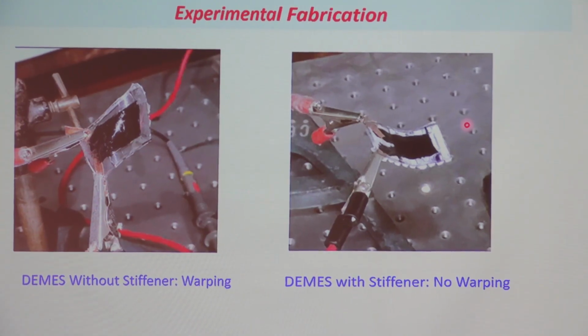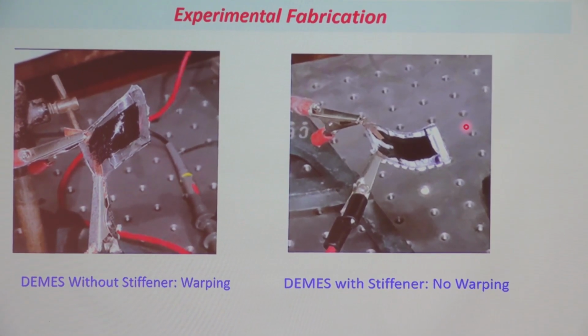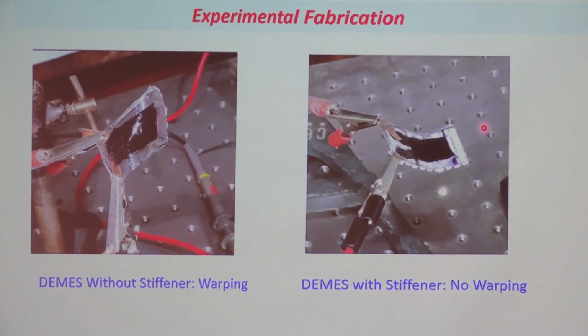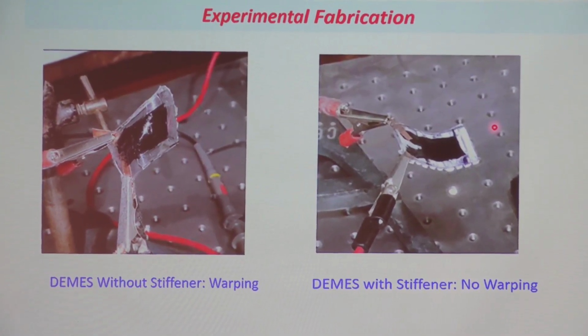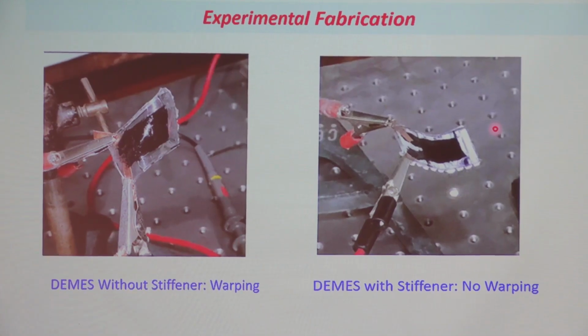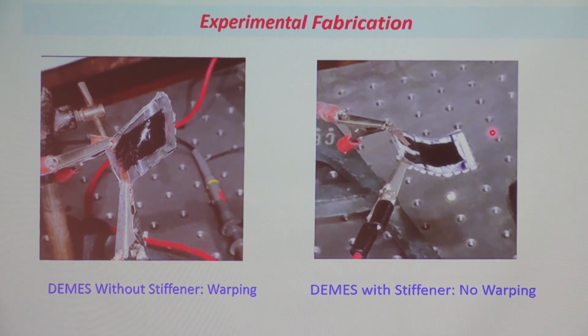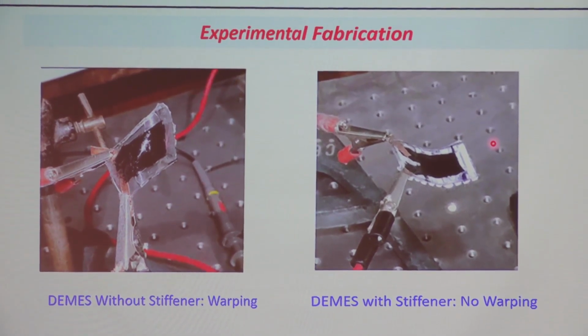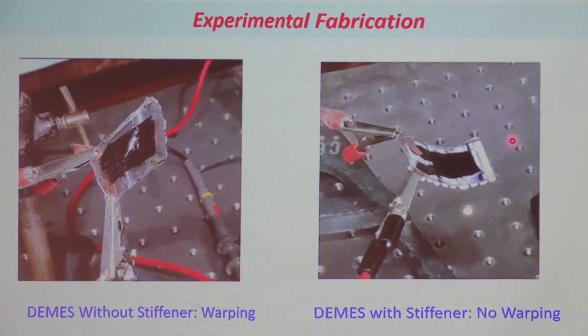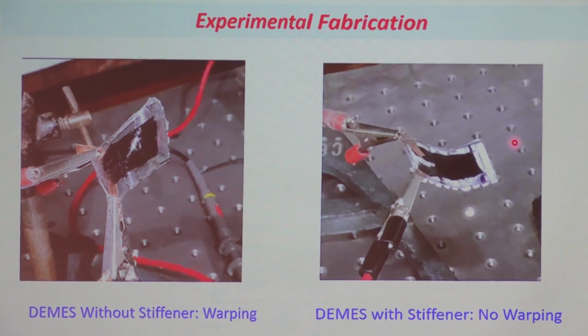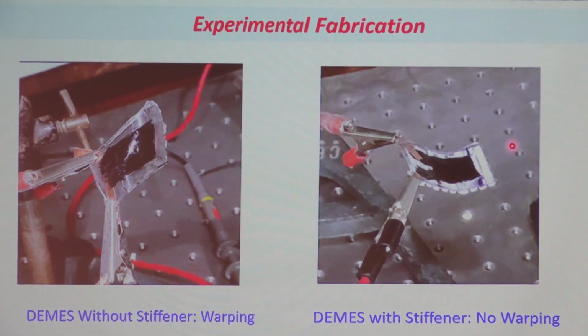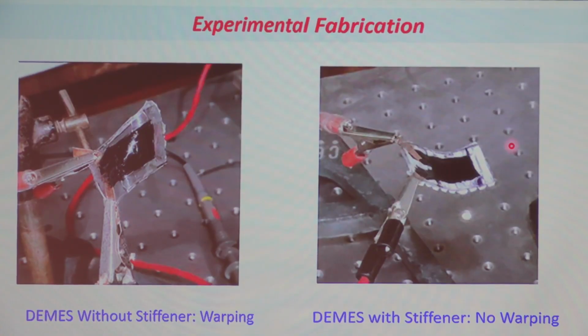So what are the different methods? Can we have any other option instead of putting a stiffener, but still get a stiffening response in the membrane? Anything you can think of as an engineer? Yes, we put anisotropy. During fabrication of the dielectric membrane, you can put some anisotropic behavior in the membrane material along the required direction. So there is no need to put all these stiffeners. You're getting my point?